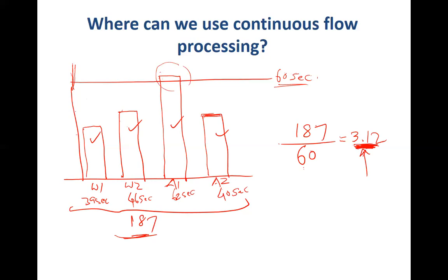And also, if possible, try to reduce the time that it takes for every workstation that would have been created by this cell that we have developed, or combining few of these activities that we were earlier doing separately, such that the time that it takes in each of these processes are just a little less than the takt time, so that we are not right on that takt time and we have some buffer, just to ensure that we are able to create the products without having to worry about being sometimes above the takt time. So that's the objective that we will be achieving through some Kaizen events, process Kaizen events.